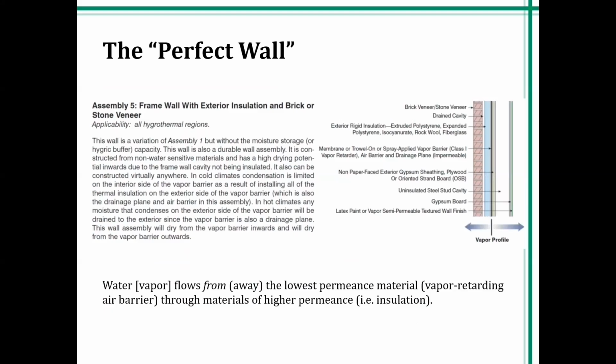We don't have much change on the interior, but the dew point location tends to oscillate back and forth, and sometimes it might go outside or inside of the rigid insulation, but the majority of its occurrence is largely going to occur within this closed cell, for all intents, closed cell foam plastic insulation. Another interesting fact about rigid insulation is the pink and the blue manufacturers' tech data, which typically cite a maximum amount of water absorption of about 0.1% by volume, as expressed as a maximum. So these are not going to be like sponges and take on moisture and then become basically saturated.